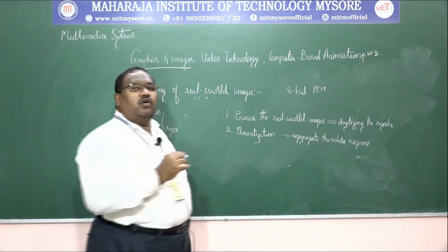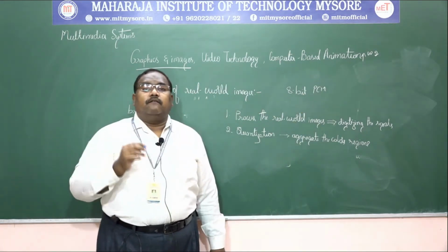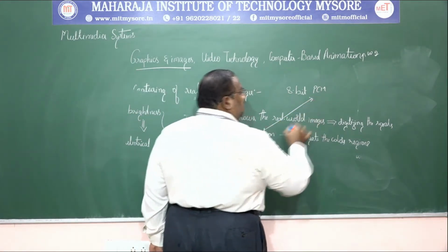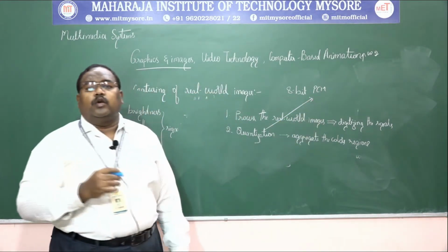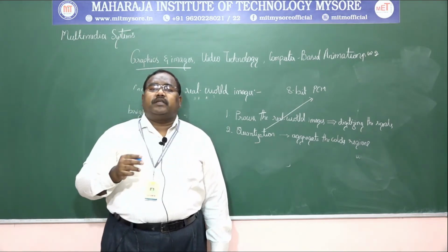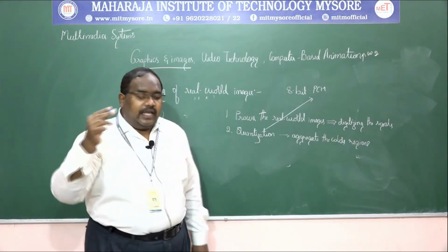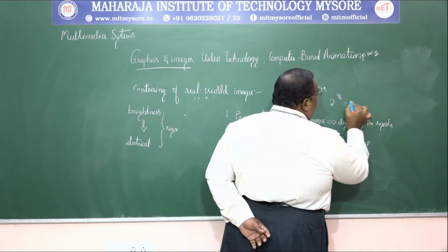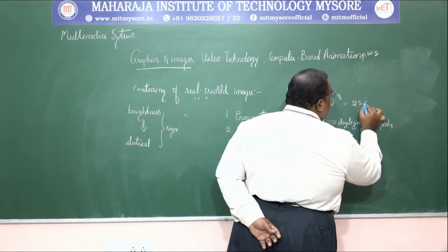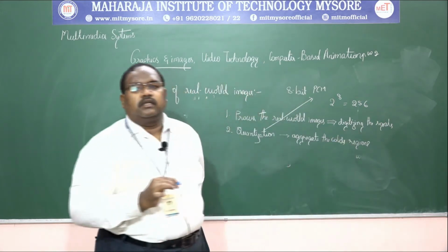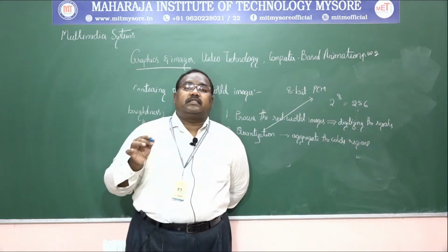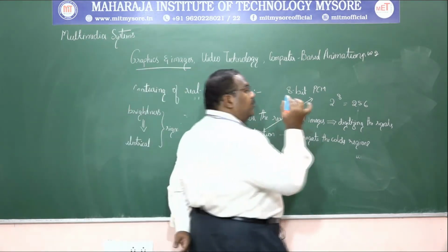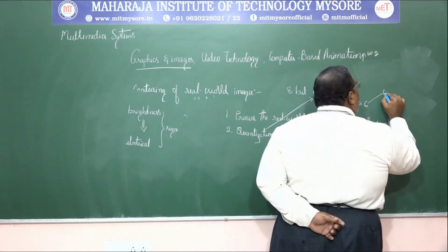That is pulse code modulation, and with respect to quantization, we do an 8-bit PCM quantization, which means we can represent 2 to the power of 8, that is 256 different colors. It might be different colors, or even it might be a gray level.